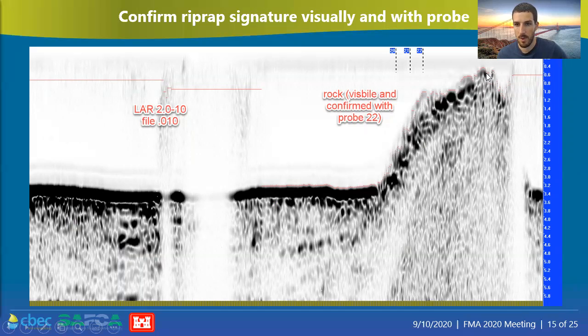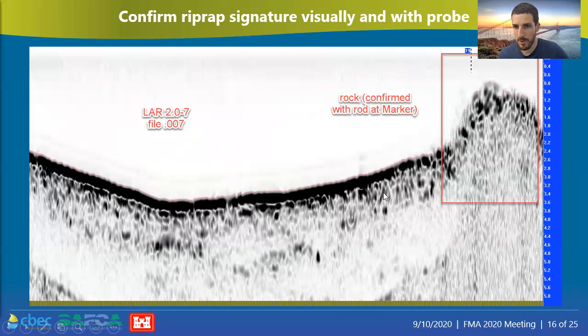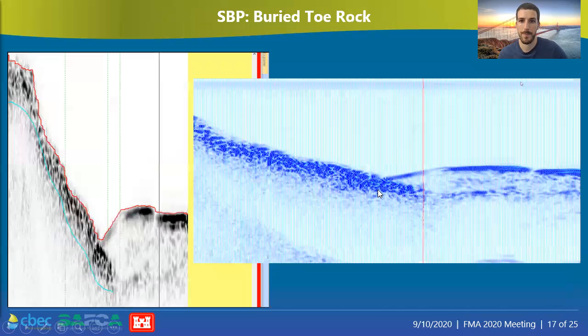So in this case, we're seeing a relatively large but mottled texture along the revetment or the riprap, and you can see that plunges a bit below the subsurface of the consistent fine-grained but harder return on the sand surface. And here's another look at that. There's a rock hump here with riprap, and then the sand, the consistent sand signature of the channel bottom.